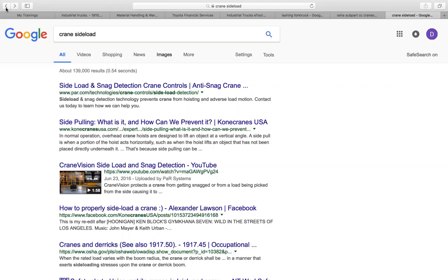A critical lift. If you look at your crane on the right-hand side, that Link-Belt, let's say in that position that crane is 100 tons. That means in that position on the short stick, with the rest of the boom in like you see it there, and properly outrigged, it should be able to pick up 200,000 pounds, 100 tons. So a critical lift would be 75 tons, or 150,000 pounds. Anything above 3/4 of its capacity would wind up being a critical lift.